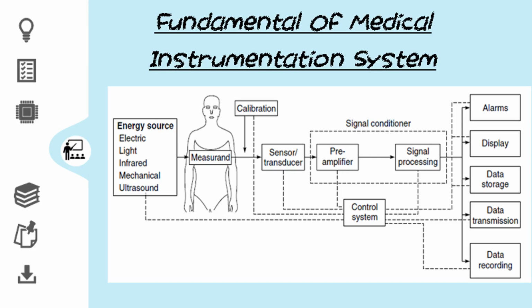Signal conditioner actually converts the output of the transducer into an electrical quantity suitable for the operation of the display or recording system. Signal conditioners may vary in complexity from a simple resistance network or impedance matching device to other complex electronic circuitry. Signal conditioning usually includes functions such as amplification. It aids in increasing the sensitivity of instruments by amplification of the original signal or its transduced form.